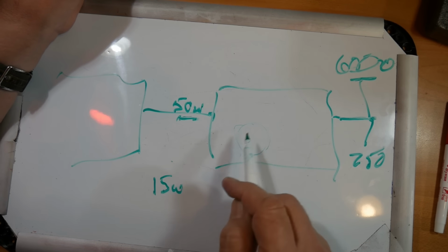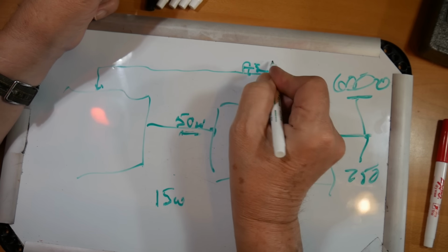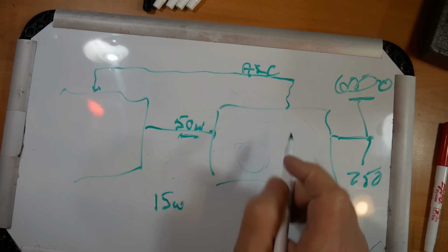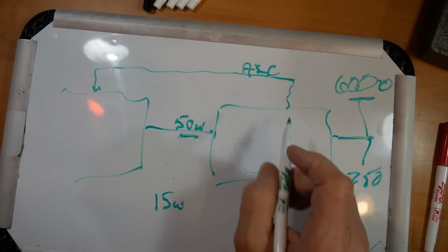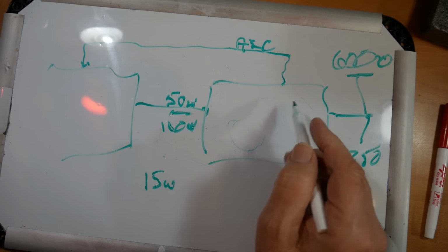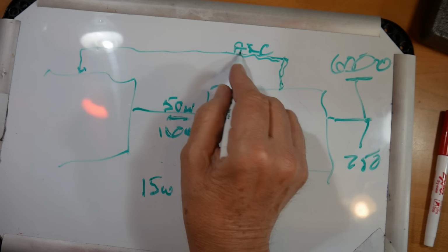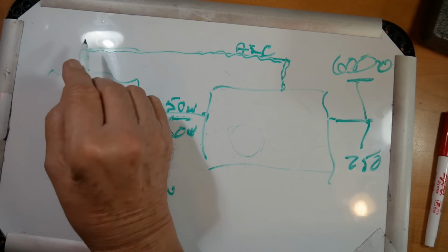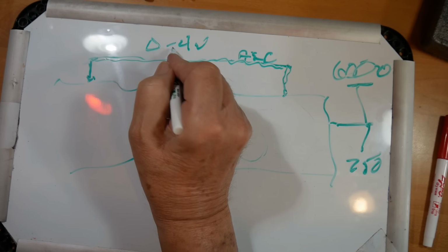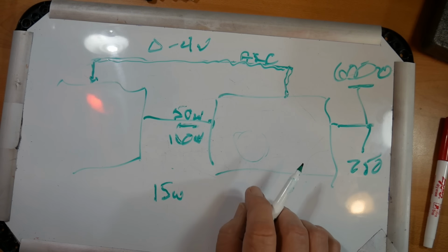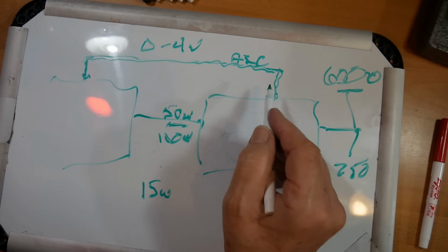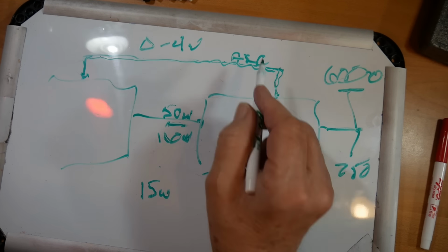can lead to distortion. So there is a wire running from your amplifier back to your radio, and it's labeled ALC, automatic level control. So if you put in 100 watts, this signal, it happens to be negative going, and it goes 0 to minus 4 volts on modern amplifiers. It can be higher on other amplifiers. But what this thing does is it turns down the transmitter power.